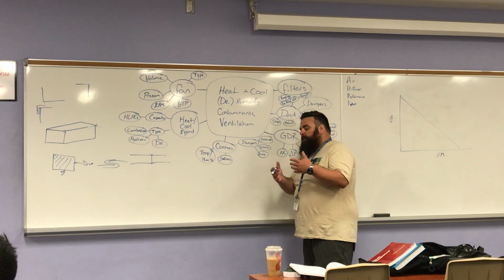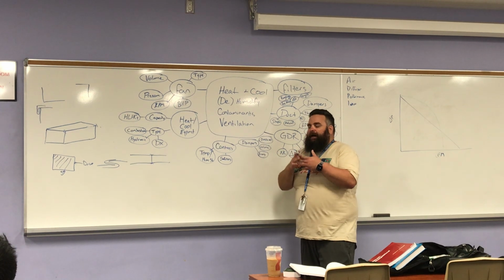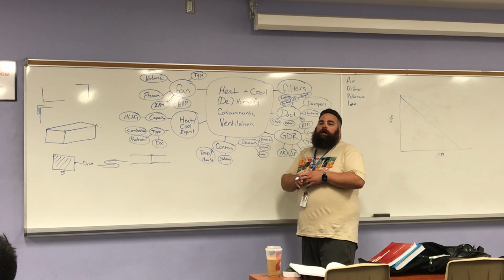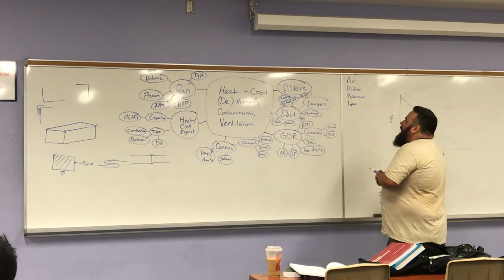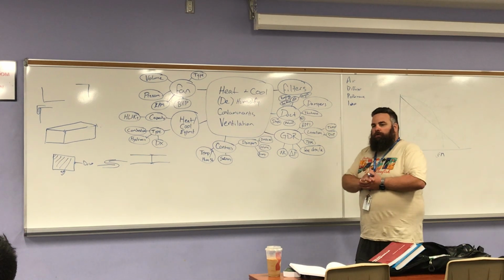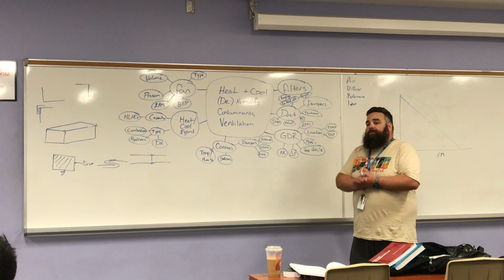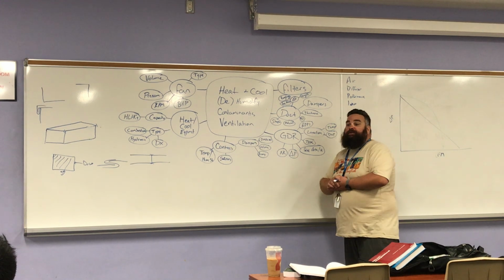So a filter will have a physical membrane that will capture particles either through direct impaction or these sorts of things, which we'll get into. An electronic air cleaner just zaps the particles. Yeah, it charges them and has an opposite charge plate that draws them, but it wouldn't be considered specifically a filter.